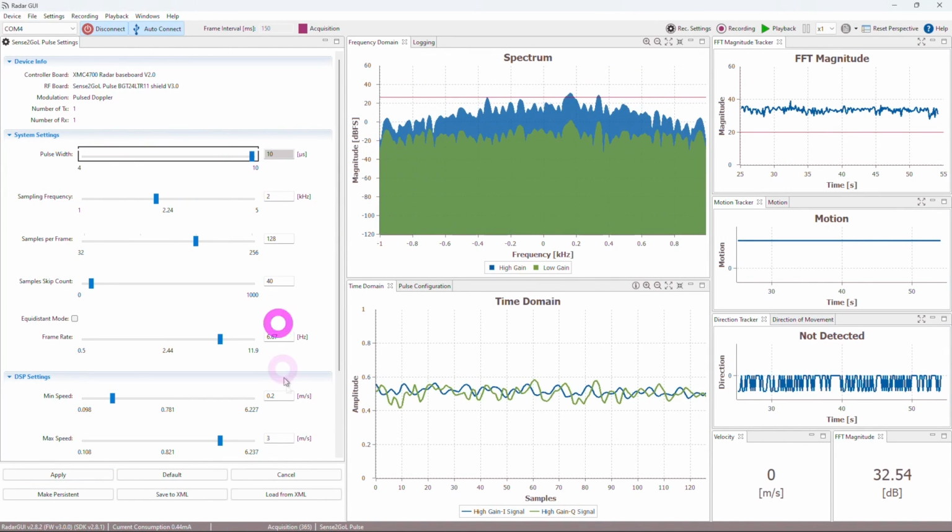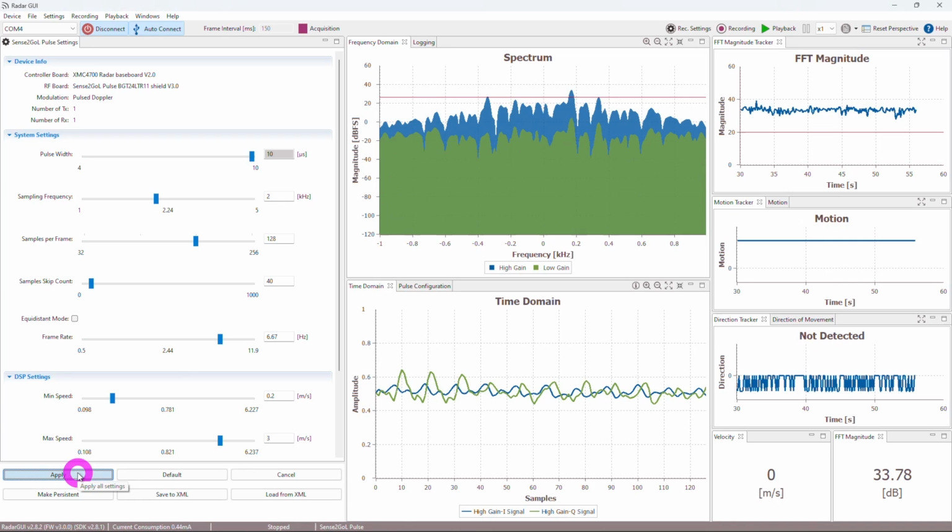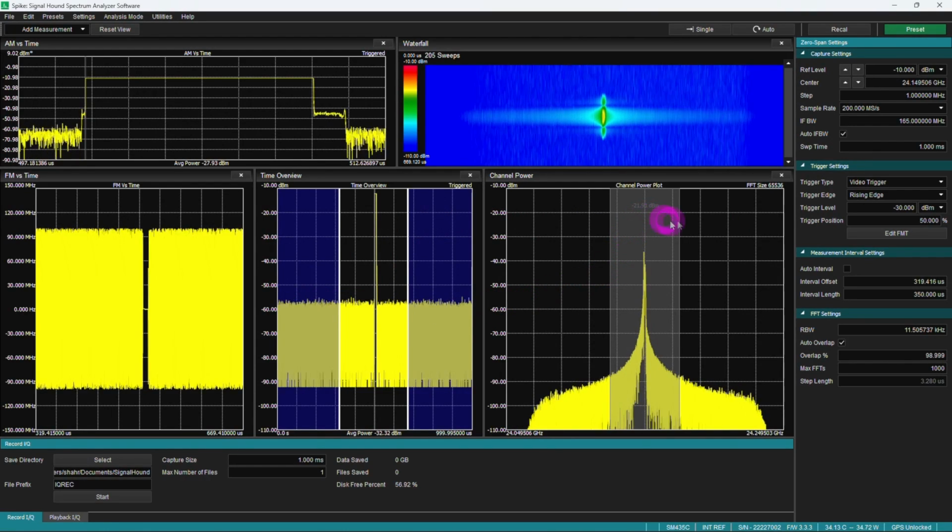So I can go ahead and make the pulses back to 10 microseconds and apply that and go back, and you can see now the power is minus 21.9 dBm, because they were turning on more power per pulse in this case, because the pulse is longer, and this of course has no issue capturing that.